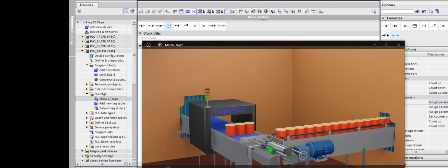Now, the idea is that this pusher will push a tray, and while this pusher is pushing the tray in this direction, this other one is going to be on hold. That means before this pusher pushes this product in this direction, the conveyor will first of all stop and be at a standstill. Remember I told you that there is going to be a timer in our design. The essence of that timer is similar to what I just explained. For this one to come here and stop, there is a timer that will make it stop. Not a timer, there is a sensor that will stop this movement.